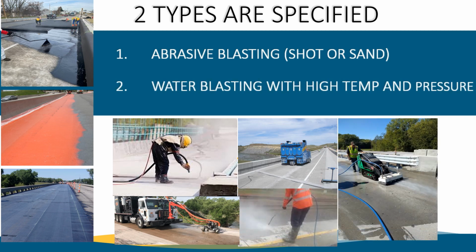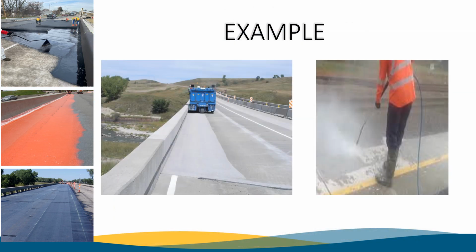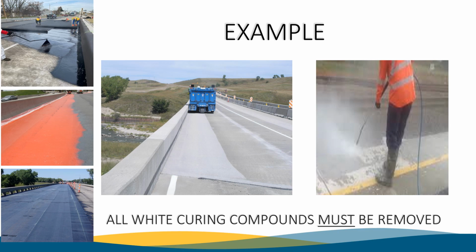The second type is power washing. It will remove any surface laitance, but it won't remove some stains on the deck, like binder and oil marks. In either case, all of the white curing compound residue must be removed.